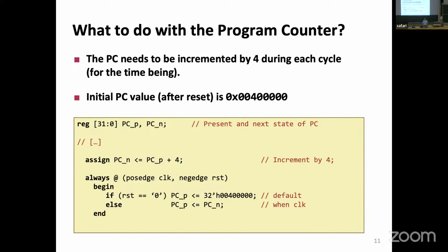Why not? We covered this, actually. It's historical reasons. There's a very long and boring story about it. Historically, ASIC designers ended up using active 0 resets. FPGA was a young child, so it came out in like end of 80s, and they asked exactly the same question you said. Why negative? We will be positive. So most FPGA designs by default use, and they had to make this difference. So the code that runs on FPGA and the code that runs on ASIC usually ends up being slightly different. There's no real reason these days; back in 1970s, there was a reason. These days, it's a historical baggage. My grandfather was doing it that way, and I will fight to my last breath that I do something like that. You're completely right.